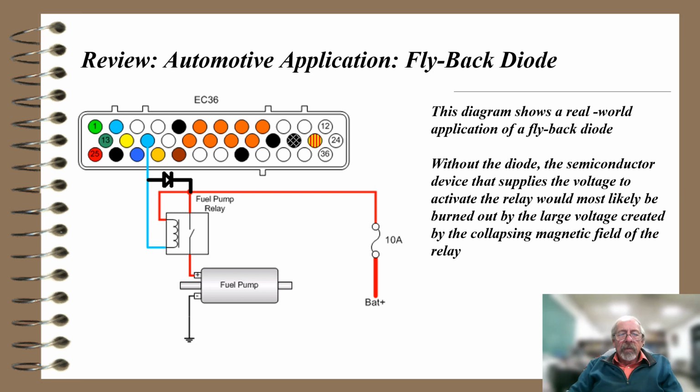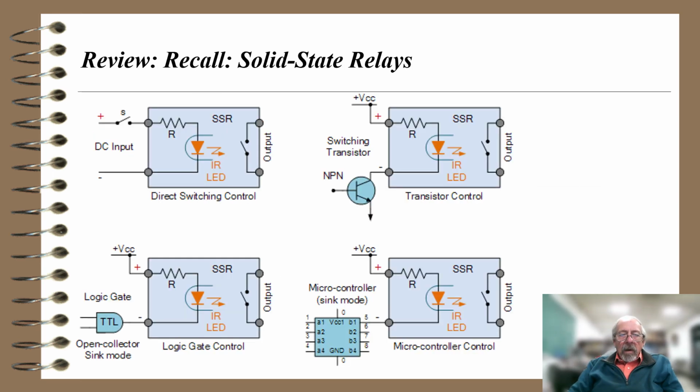You see the fuel pump relay. So again, there's a diode across that. That's a flyback diode again, to not burn out the lead that comes from the blue wire there, which is from some type of switching transistor. We talked about this before. We call it solid state relays.